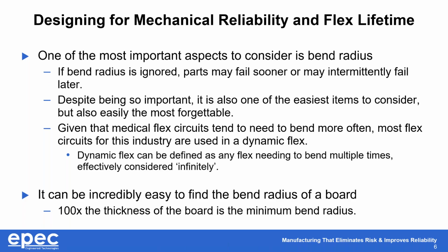And so it's unfortunate, because bend radius is actually one of the easiest things for a flex circuit to calculate, to determine, to test. But most tend to get into the weeds of how complex a design can be and just kind of forget about the bend radius, or in some cases may not even consider it to begin with. They may not know to consider it.